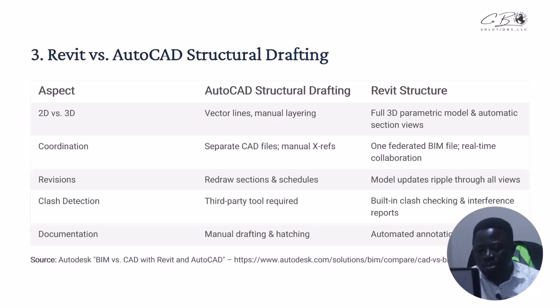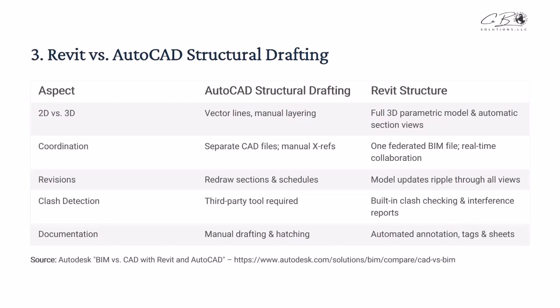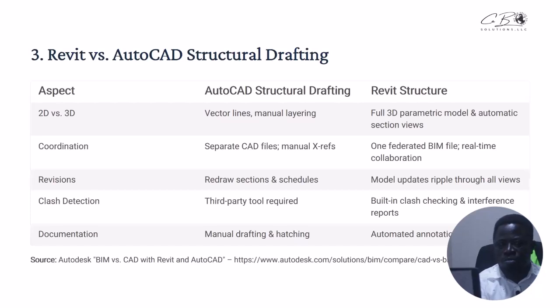It's actually very, very difficult to do that. When it comes to BIM, it's simple because everything you do updates automatically. There's something we call bi-directional associativity. It's a function of Revit or BIM. This is big English. All it means is that what you do in one place updates automatically everywhere.